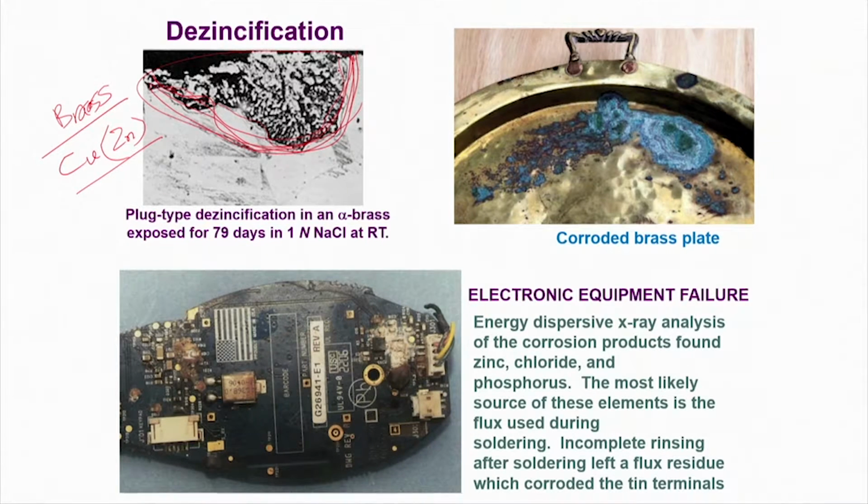So we also would have seen all these brass wares, the brass plates, flower vases, various kinds of art objects and so on. And this kind of bluish green corrosion product, patina, is very common to form on such brassware or brass plates, even copper plates and so on. So these are again corrosion products, some kind of a sulfide, and these are because of the continual corrosion happening.